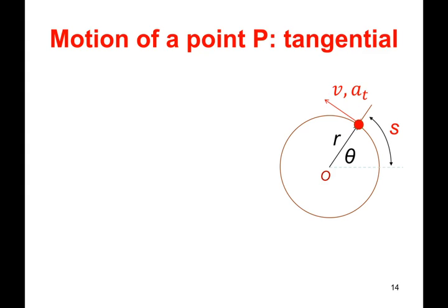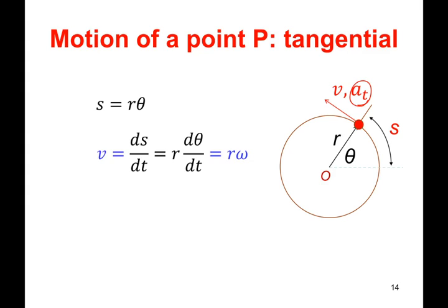And you always have to keep in mind that whenever we are talking about acceleration in these lectures, we are talking about the tangential acceleration. If we are talking about the acceleration of a point P on a disk or a ring or whatever, it is the tangential acceleration. So to find the linear displacement, we essentially have to find the arc length, and we already have an equation for that: your curvature radius multiplied by theta, the angular displacement.